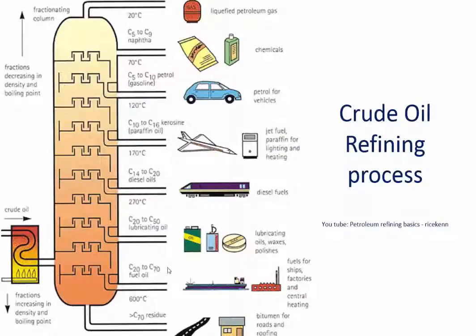So they take the crude oil and then they refine it. It goes into a fractioning tower or column where they increase heat. They have this full of crude oil, and basically the lighter fractions are taken off as gases. So we get our LPG, liquid petroleum gas, off at the top, some lighter gas chemicals, and then we get petrol and kerosene. We get our diesel oil, which is often known as distillate, and we can have heavier grades of diesel oil.